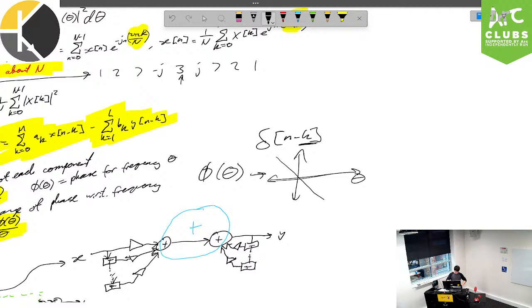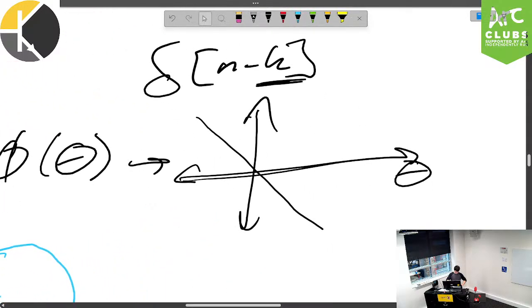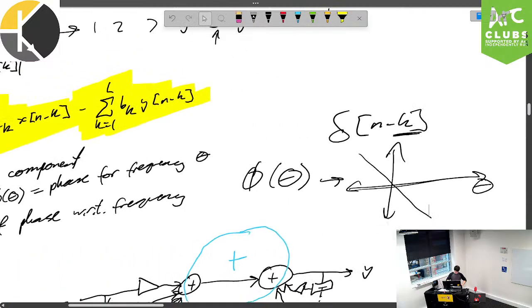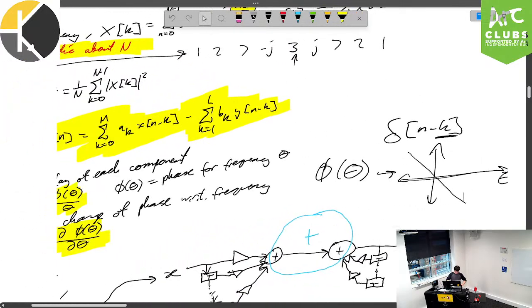Now, what this implies is that your delay is proportional to your frequency, and so the delay we're talking about is by some constant time factor. Okay? So you can tell just by thinking, if I have a high frequency and I'm delayed by a specific amount of time, I will be delayed by a greater phase than I would be if I was just working with a small frequency. Okay?